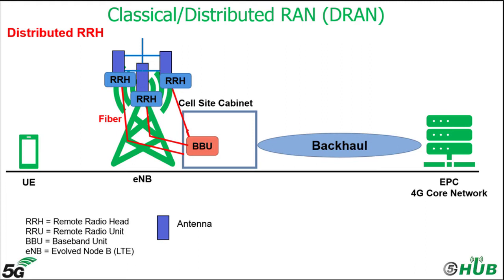Due to their lower capex and opex, these RRH are currently being deployed not just for new technologies like LTE and LTE Advanced, but also in new and replacement infrastructure for older technology 2G, 2.5G, 3G. The RRH can be linked to the BBU or baseband unit by an optical single-mode fiber using a standard interface with a digital radio signal such as CPRI or Common Public Radio Interface.